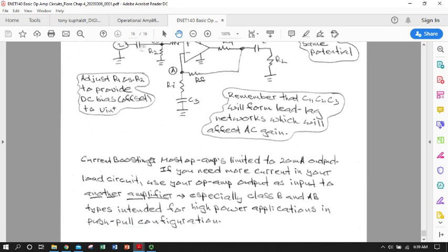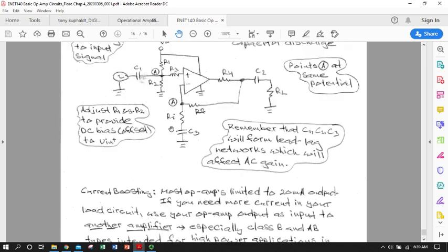And this is very likely, by the way, one of the reasons why our classroom function generators are so limited in their current output. They very likely are relying on not a lot of post-amplification, signal amplification boosting. Maybe they just have a single 20 milliamp op-amp and a single booster stage after that. If you wanted to get 1, 5, 10 amps or something out of that, you would have to have a cascade of current boosting coming after your voltage signal boosting, and then design it such that you didn't interfere with the fidelity of the voltage signal that you just worked so hard to preserve here.